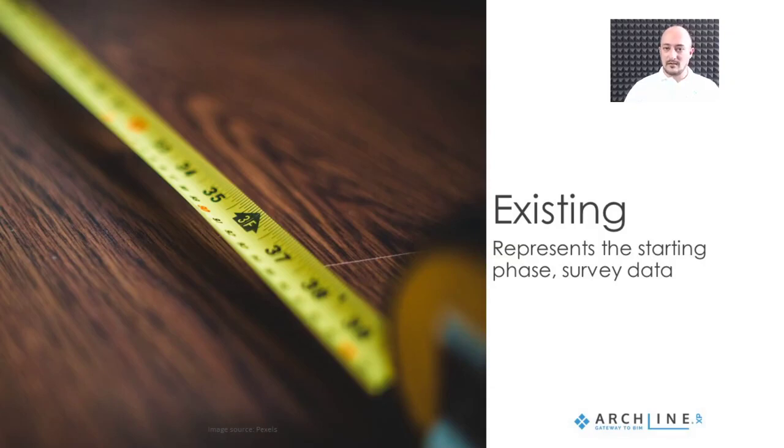What you create by default, everything lands in the existing design phase, which by default, we can say, represents the starting phase, or it could represent the survey data, or it could simply represent the building, because sometimes you just do not do separate phases. In that case, you don't have to worry about anything. It just works fine with single projects as well. So you don't need to do anything if you do not want to create phases.